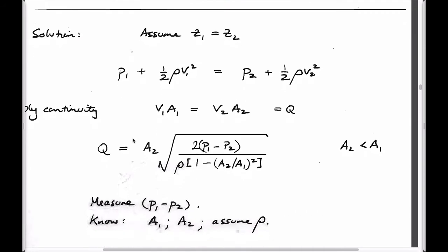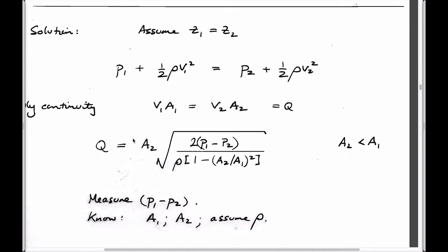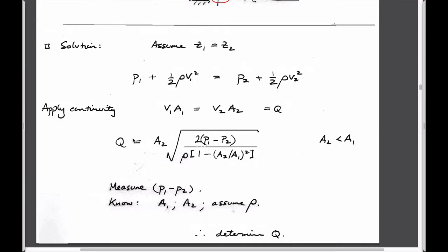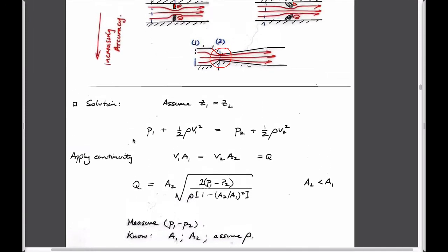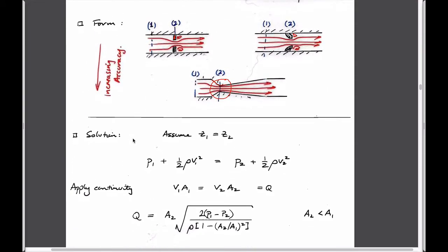And so if you want to solve for the pressures or the velocities in the system, it's pretty straightforward. We can write our Bernoulli's equation between 2 points. It doesn't necessarily have to be horizontal, but we make our life easier if it's horizontal. Then this is the appropriate Bernoulli equation. We don't know what this is. We don't know what this is. We'd like to know what either of those are. We only need to know one.